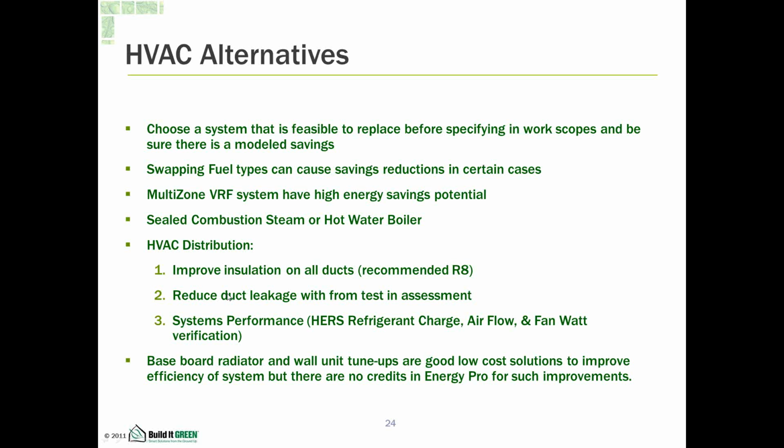Improving your HVAC distribution, like your ducts, making sure all the ducts are insulated to the recommended R8. Reduce duct leakage from test and assessment, preferably to a passable HERS percentage. And it's also a good practice, if there's cooling, to do a systems performance verification using HERS protocols for refrigerant charge, airflow, and fan watt verification.